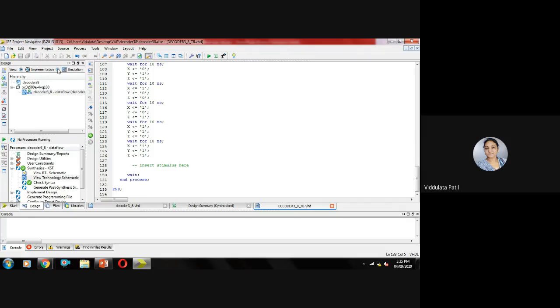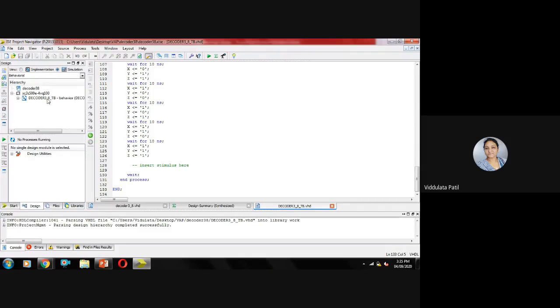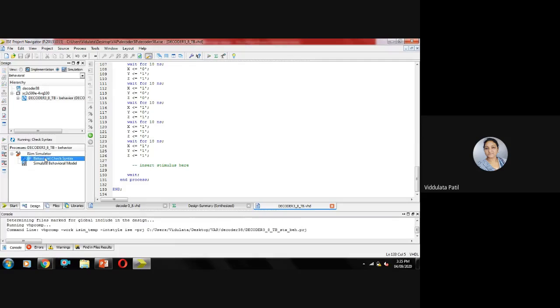And now just go for the simulation, click on your test bench program. Then here in the processes you will get an ISim simulator. Expand that and check for the behavioral check syntax. Click on that. It is completed successfully. So now let us check for the simulate behavioral model.